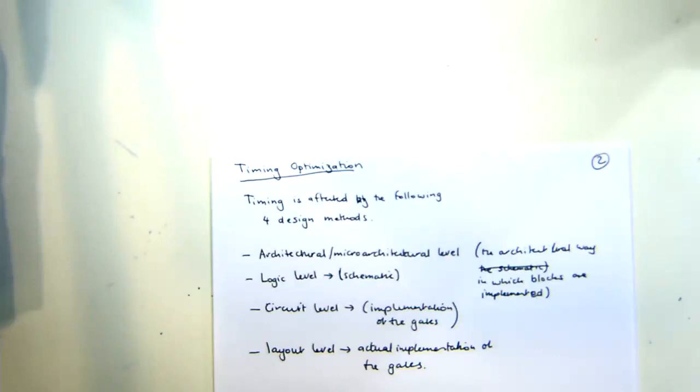okay, so you do it that way, right? And then you can focus on making the ANDs and the ORs a little bit faster. You can focus on making the multipliers faster, and maybe you'll get it 30% faster, all right? But if you realize that, hey, if I want to do a Fourier transform and I implement it as a fast Fourier transform, in terms of using butterflies and multipliers and reusing all those components, I can get it probably a factor of 1,000 faster, right? Because what you're doing there is the architecture itself, the way that you're doing the calculations, is different.